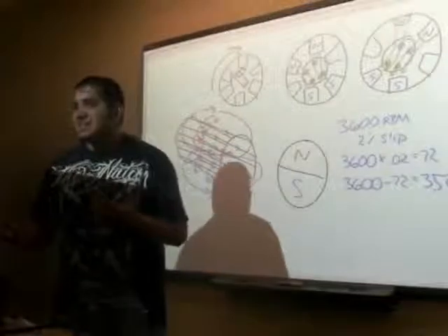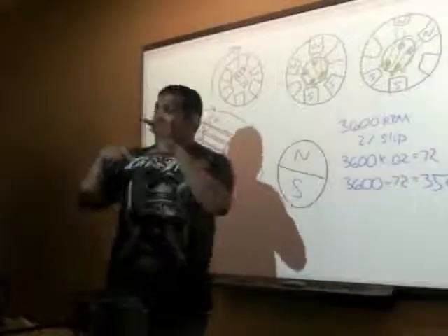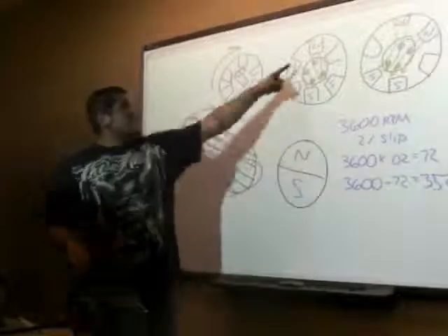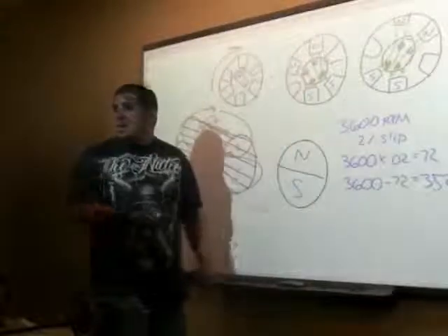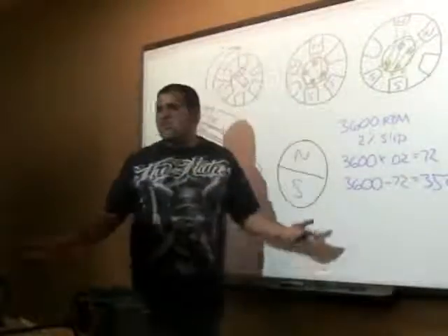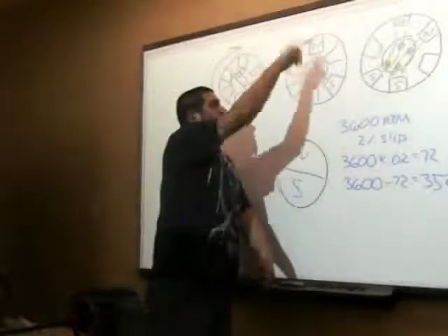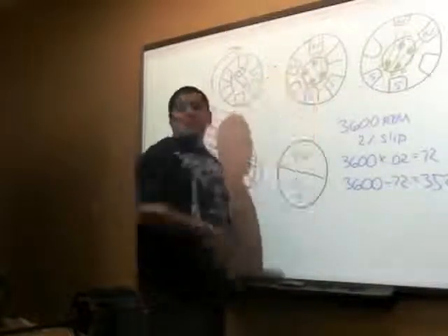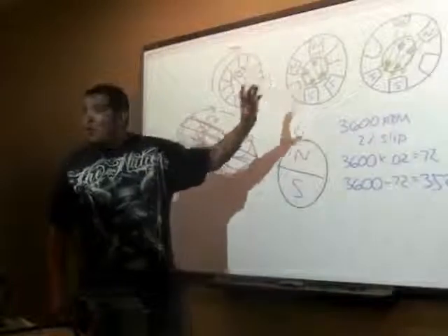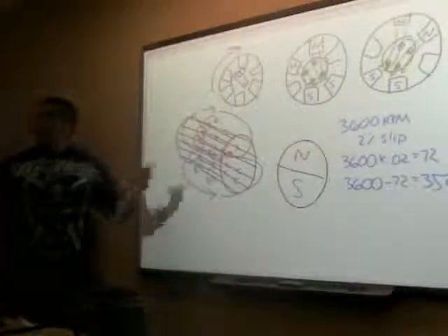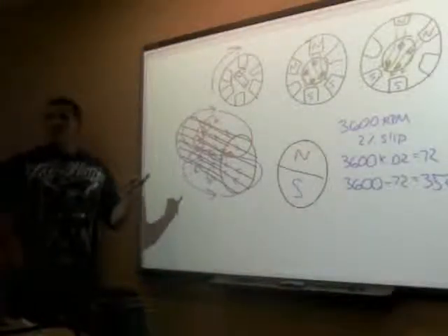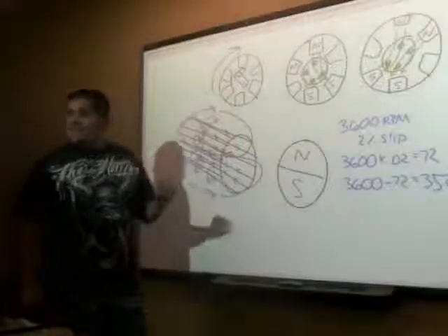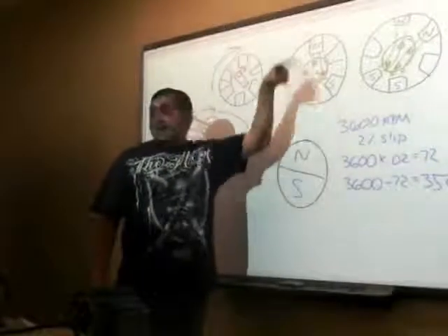Then what happens again? If it's slowing down, it starts cutting. These magnetic fields, they don't stop, right? The stator fields, they keep going. They don't care what's going on in the rotor. They just keep going. So if this slows down, and this is still going at the same speed, we start inducing more current back onto the rotor. What happens then? We strengthen these magnetic fields, and we catch back up.